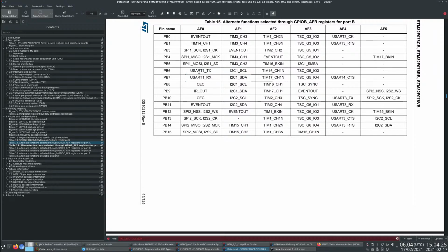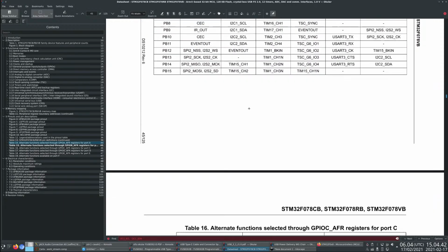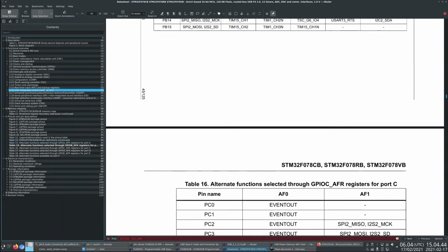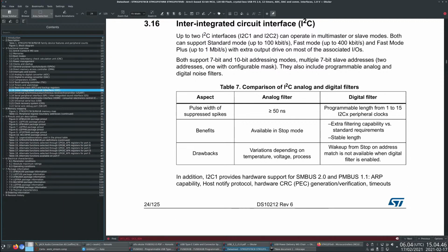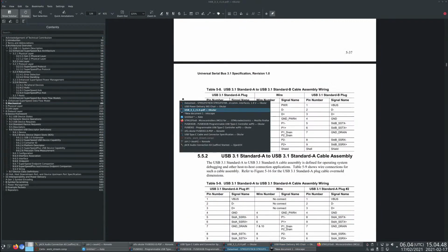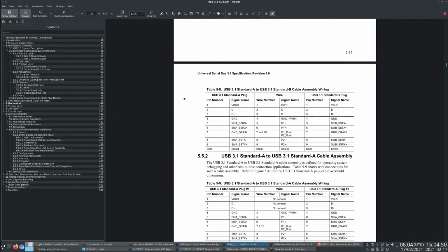So if I get that polarity, I can try to make it the same as on the Mac, for example, and then you would be able to use these. And similarly, I2C2 is on the same as one of the USART3 TX and RX sets. And I don't know if we have any others. Is it just 2 I2C interfaces? Yeah, it's just 2.